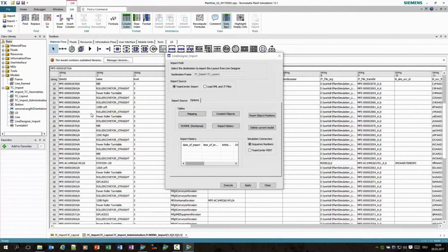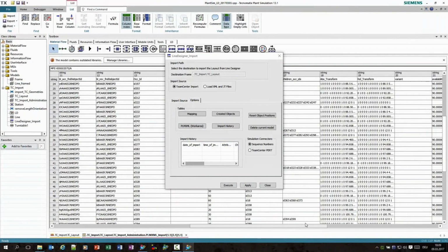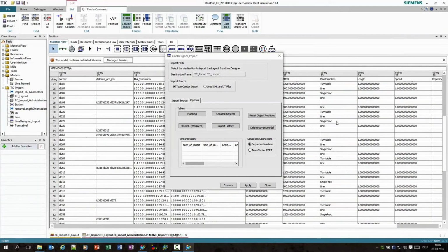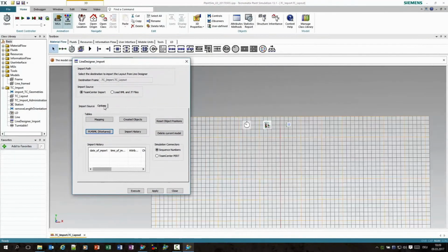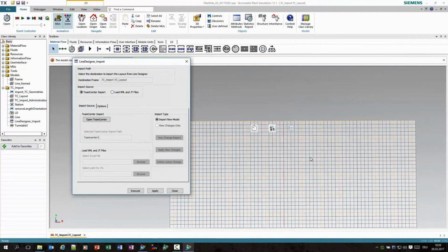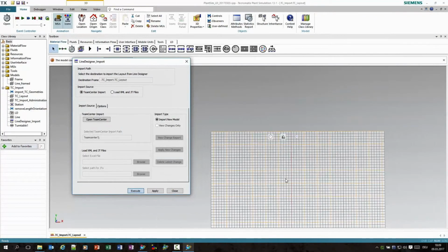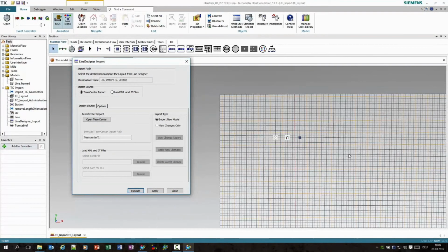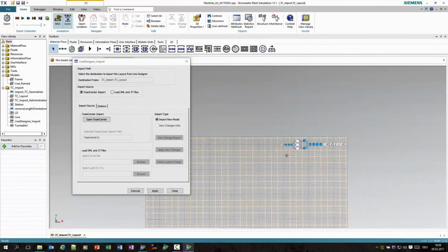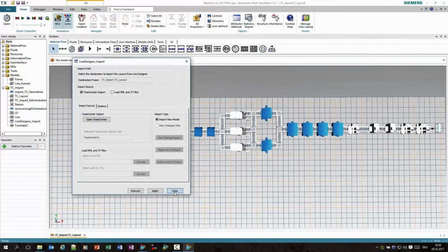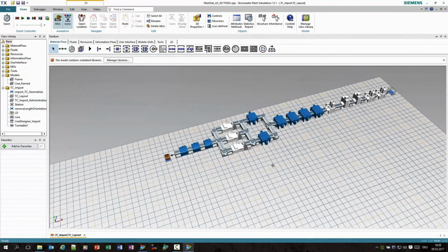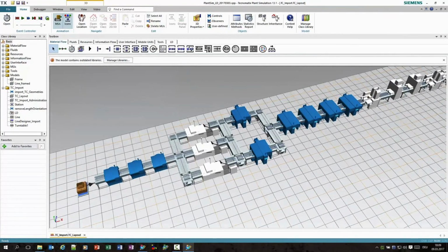But you can see I have all types of individual components, and each of these have all these parameters built into it because I put them into my library. So it knows the line speed of conveyors. It just doesn't know the length. So when it gets the length, it goes by the line speed. It multiplies that out to see how long it takes to create that. So it took that line, imported it in, and I can actually analyze this for throughput.